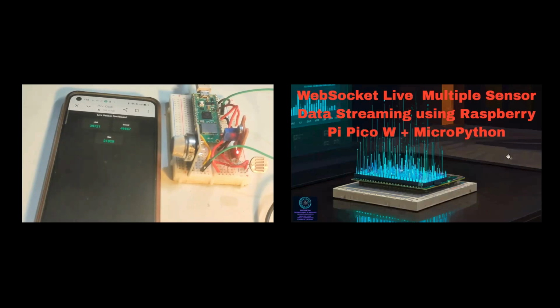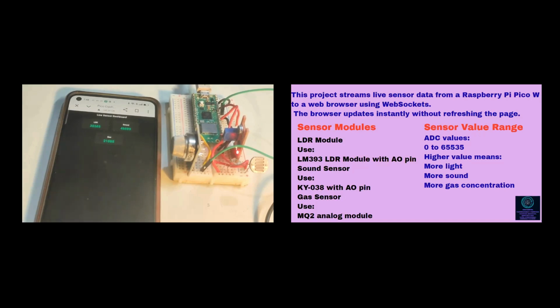So one more project today on a new topic. The topic is WebSocket: live multiple sensors data streaming using Raspberry Pi Pico W with MicroPython. This is our project. We will go through the project, what it actually is, and we'll see the difference. The project streams live sensor data from the Raspberry Pi Pico W to the web browser, as you can see here. Using WebSockets, the browser updates instantly without refreshing the page. This is the advantage of the WebSocket.